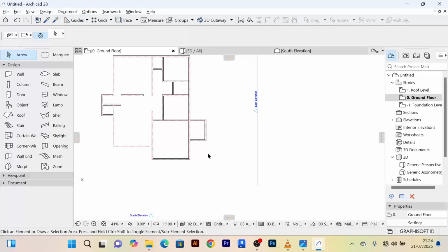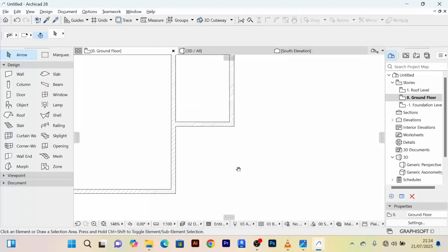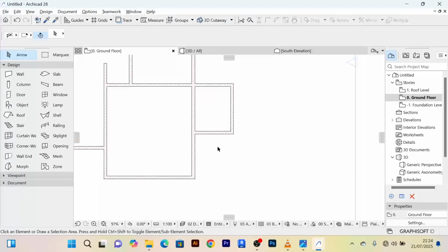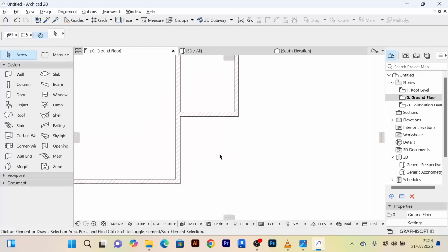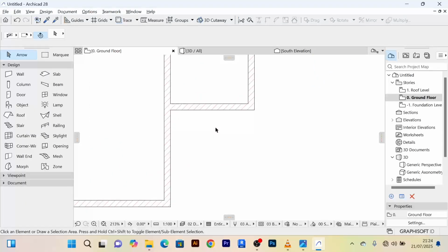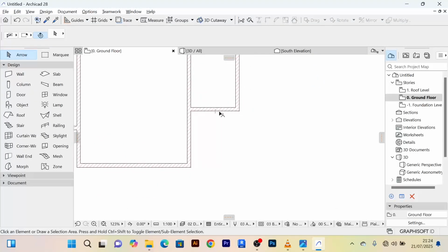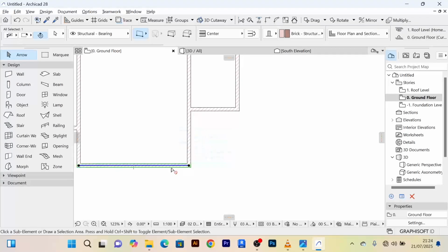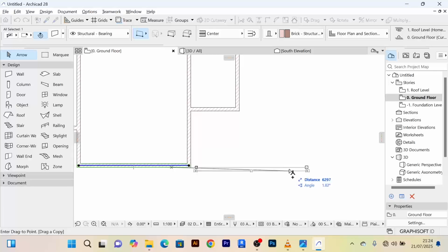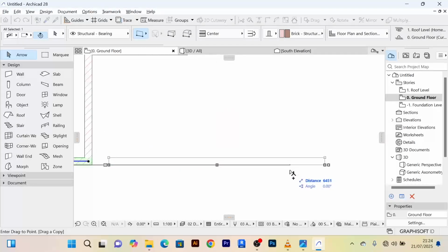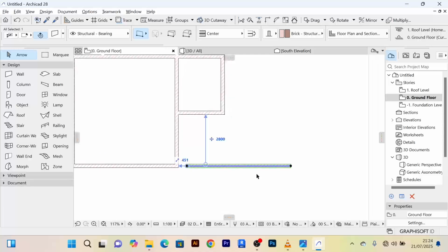So now let me create my duct. I want to create it here so that when we come to this project again, we shall not struggle with creating new walls. So I'll just simply drag a copy from maybe this one, Control Shift D to drag a copy, and make sure it is going straight, just like that.